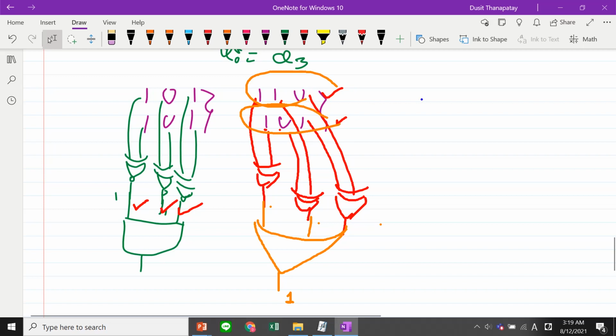If you want to check whether it's greater or not, for example, if this one is 1 1 0 and this one is 0 1 1, okay, we may take the MSB first. If this is 1, this is 0, that means this is greater than this one. Okay, if it's 1 1 0, it may be 1 1 1, something like that. You must check whether this one is equal or not, this one equal or not, right?